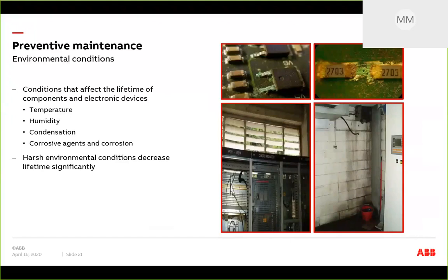but if the air and the temperature of that room isn't good, over time it may take 2 years to develop like it looks on that picture, and then things leading up to it get intermittent, and eventually they just fail. But it many times attacks those smallest components and slowly grows. Was it you telling me, Matt, that one of our customers was actually washing the boards in a washing machine or a dishwasher? I think like a dishwasher, yeah.